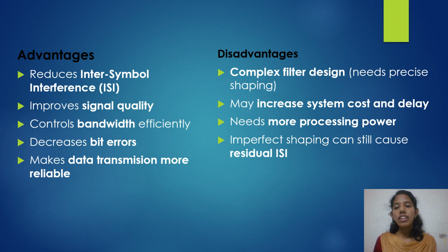Disadvantages: complex filter design, needs precise shaping, may increase system cost and delay, and needs more processing power. Imperfect shaping can still cause residual ISI.